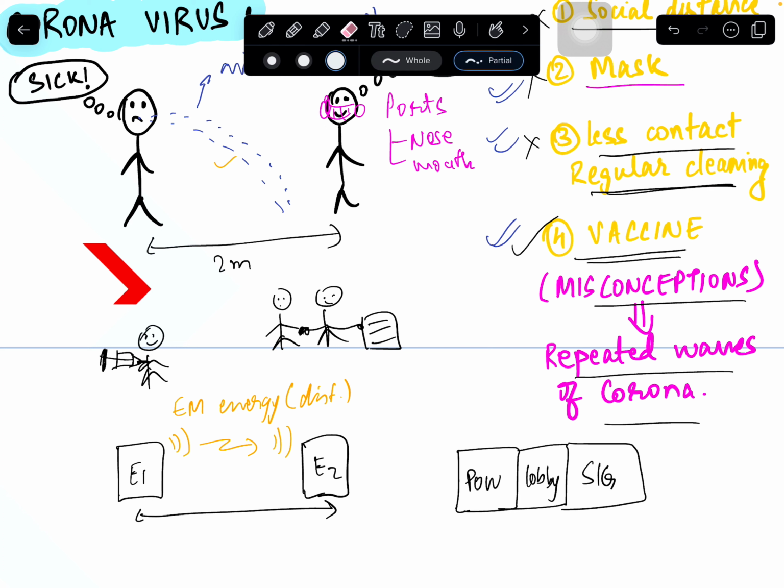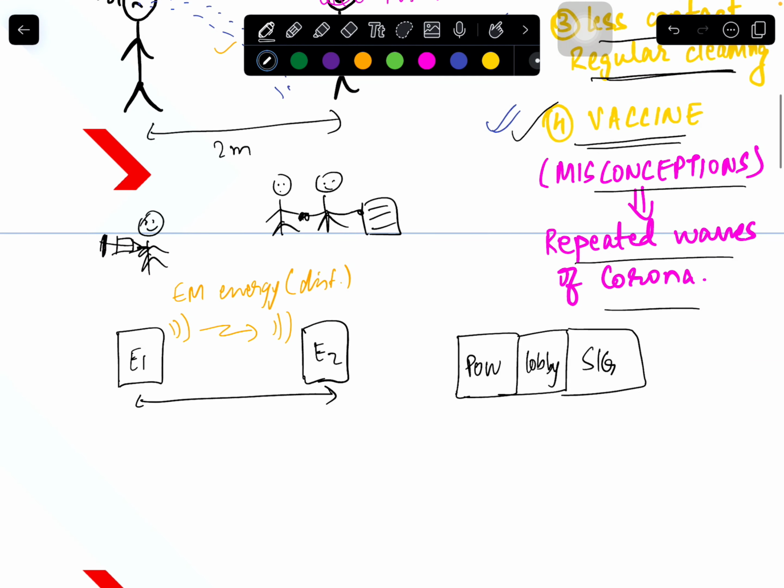So maintain social distancing. The same is for cables, high voltage cables and, suppose, control cable. So this is our high voltage cable and control cable. They say to prepare proper segregation. It can be 600 mm or 1000 mm depending on the standard which we are following. But we will talk later about the standards and about the cable tray. You can reduce it to 300 mm also by doing some mitigations, by providing perforated cable tray, covering them. All those things will be covered later.